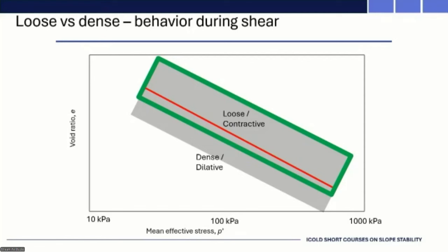It's in that little region between the bottom of that box and the critical state line. So it's not saying it's only above the CSL, but I guess based to some extent on back analysis of failures and maybe some inherent conservatism, the actual boundary is taken as parallel to the critical state line, but offset by minus 0.05.